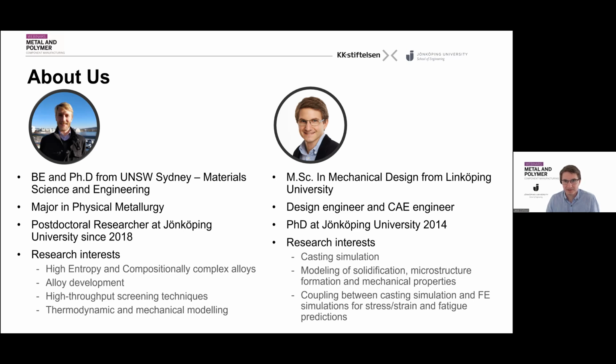Then I returned to academia and did my PhD at Jönköping University. I finished in 2014 and have remained here since. My research interests include casting simulation and the modeling of solidification, microstructure formation, and mechanical properties in different ways. Especially my focus is on the coupling between casting simulation and finite element simulations, both for stress-strain and for fatigue predictions.